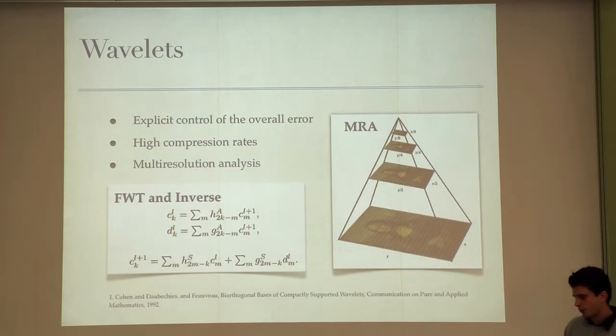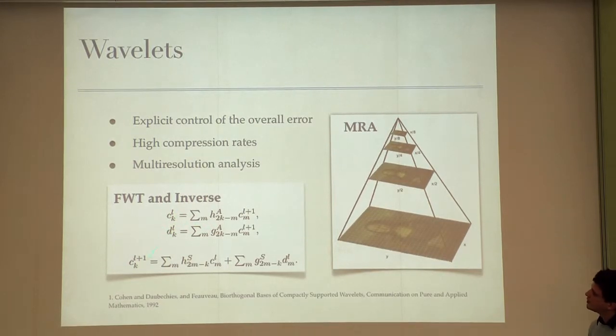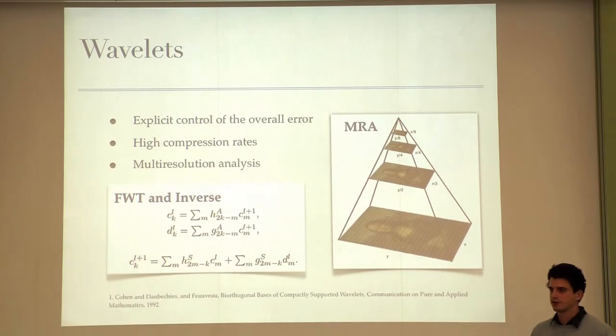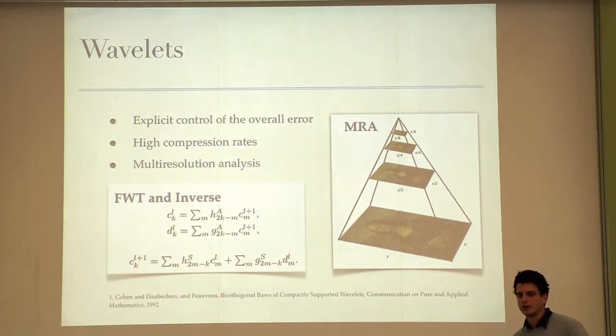Now, how can we switch between one resolution and the other in some region of the image? Well, this is done with a forward wavelet transform, where essentially we apply an analysis step where we want to get rid of negligible information in order to fill up the next coarse level. So we take a signal and decompose it into two different signals. One is called details, because they are supposed to be the negligible ones. The other one is called the scaling, which is the information that is further processed to generate a coarse representation of the signal. Now we can also do the inverse step. Given a coarse representation and some details, we can generate the finest scale. So this consistency between going to high resolution and low resolution is a very good discretization point that we can apply on the physics that we are simulating to switch resolution.